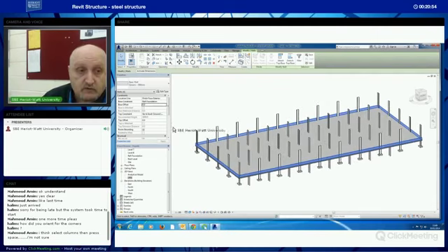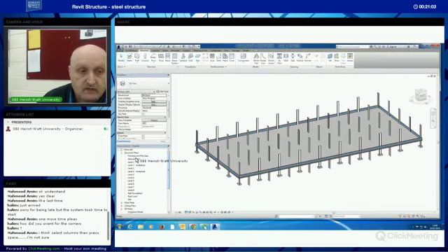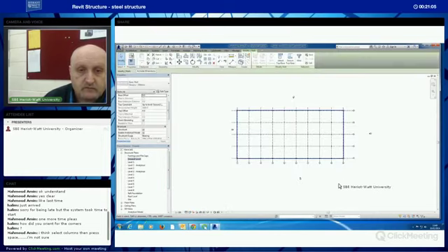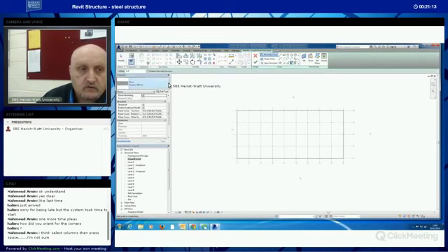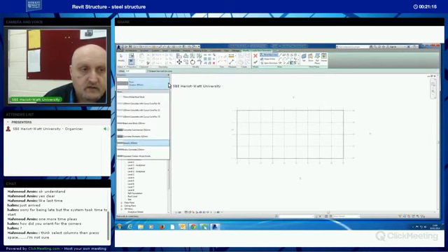It's quite straightforward. It's a structural wall, we know that. I'm just going to check that this in fact says structural in here, and this says bearing, and it does, so I'm quite happy. So now I'm kind of coming out of the ground. I'm going to go to ground level. I'm going to put a floor in. All the items put in will be structural model.